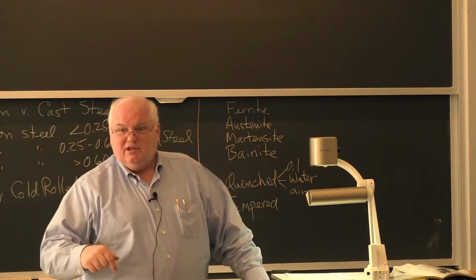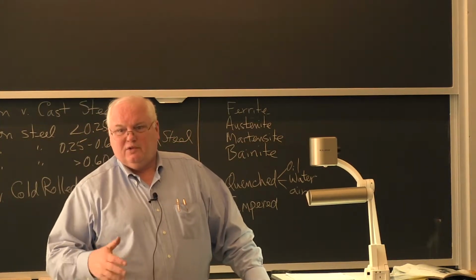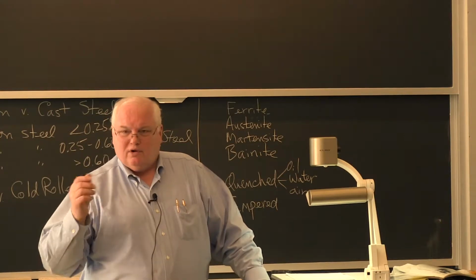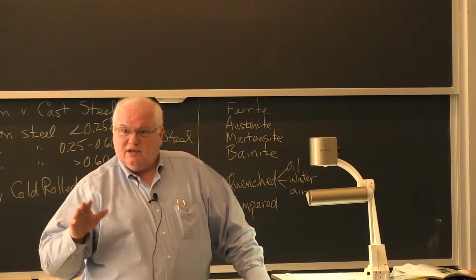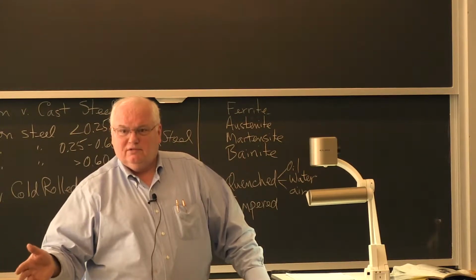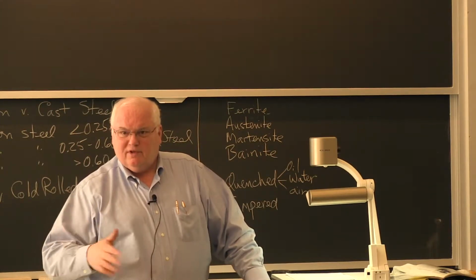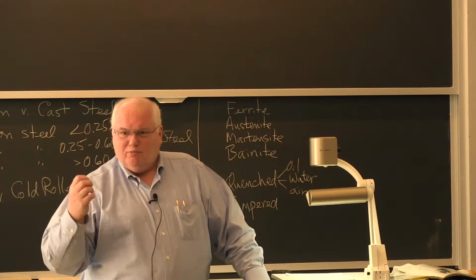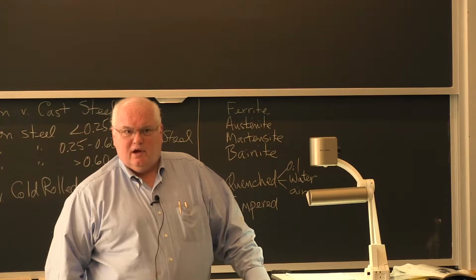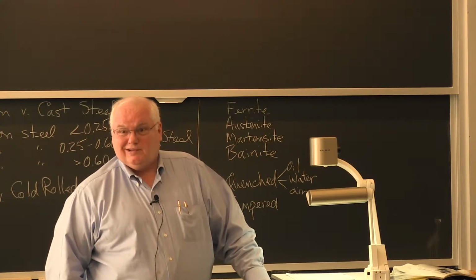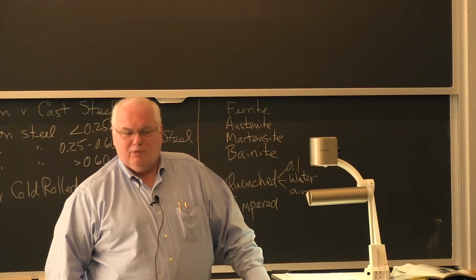It's easier to cut steel than it is to cut cast iron with all the hard particles and impurities in cast iron. Good soft cast iron cuts like butter compared to steel, but the old dirty stuff with all the impurities has got hard particles and just dull up saw blades. Okay, they often use carbide saw blades to cut cast iron, believe it or not, for old cast iron pipe.